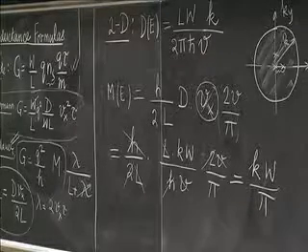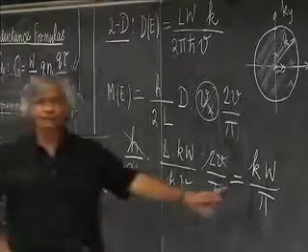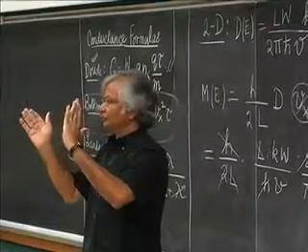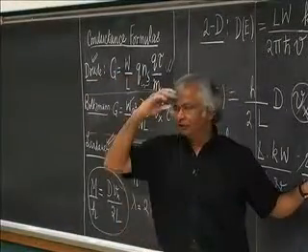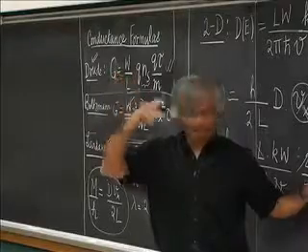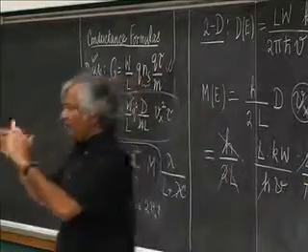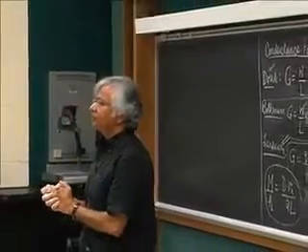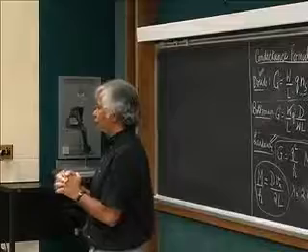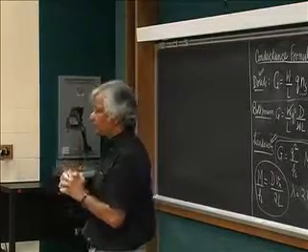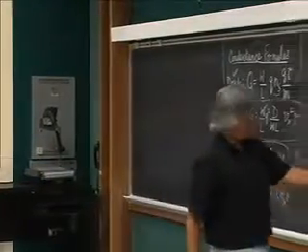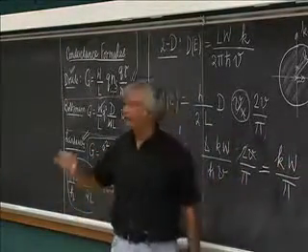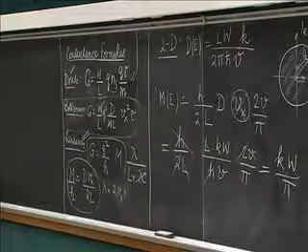Indeed, this viewpoint is usually more well known. The way you think about this is, you've got a certain width, how many wavelengths fit in? Because k you usually think of as 2 pi over the wavelength. So this tells you that in a given width, how many half wavelengths can fit into it. That's the viewpoint that comes naturally if you're thinking of microwave waveguides, and that's how usually people think of modes. What it shows you is that the number of modes really depends on k, as kW over pi, irrespective of the E-k relationship.